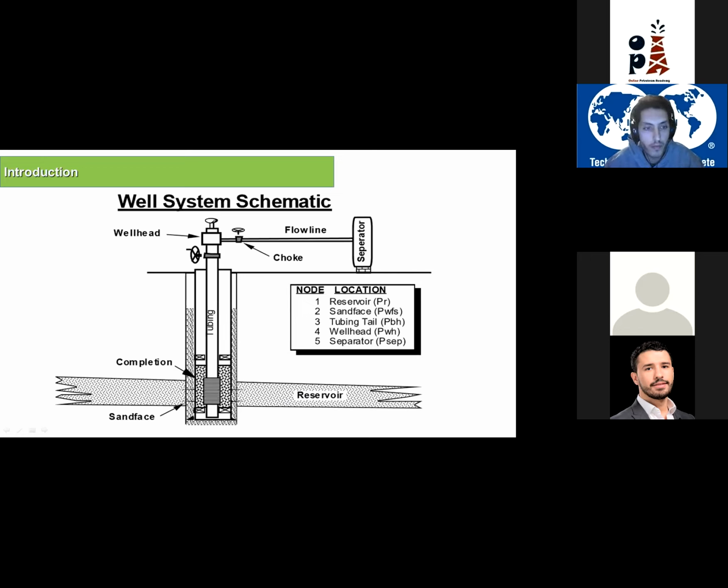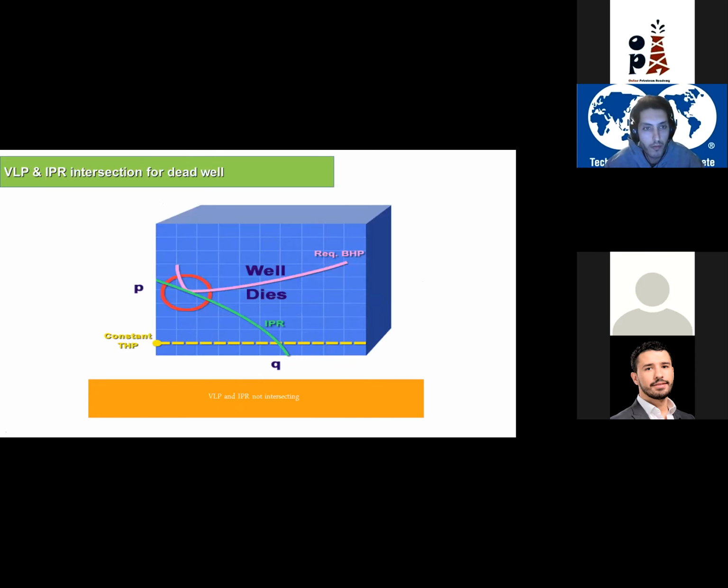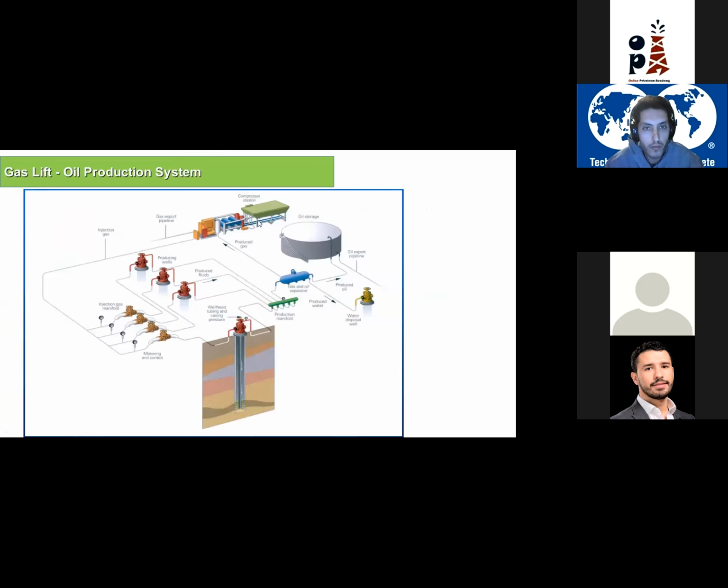So I'm producing. I have a BHFP here of 1,500, and the fluid goes up to a tubing pressure of 200. Then this fluid is moved, separated and so on. Then I have my gas here, at 200 psi or 100 psi, and it is compressed. The pressure is high. I make it reach 1,000 and then I start to inject it from here.